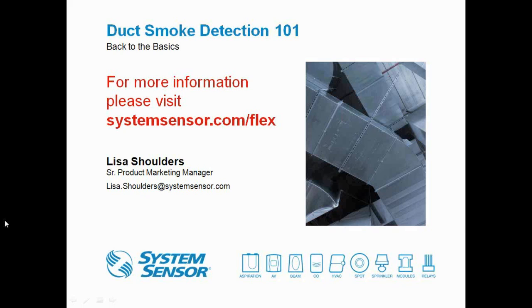You want to ensure that the sampling tube covers a minimum of 2/3 of the width of the duct. So if it is doing that, you'll still be getting a large enough sample of the air that's moving through the ductwork if it's just 2/3 of the way. But obviously, having it extend all the way across the duct is good practice as well.